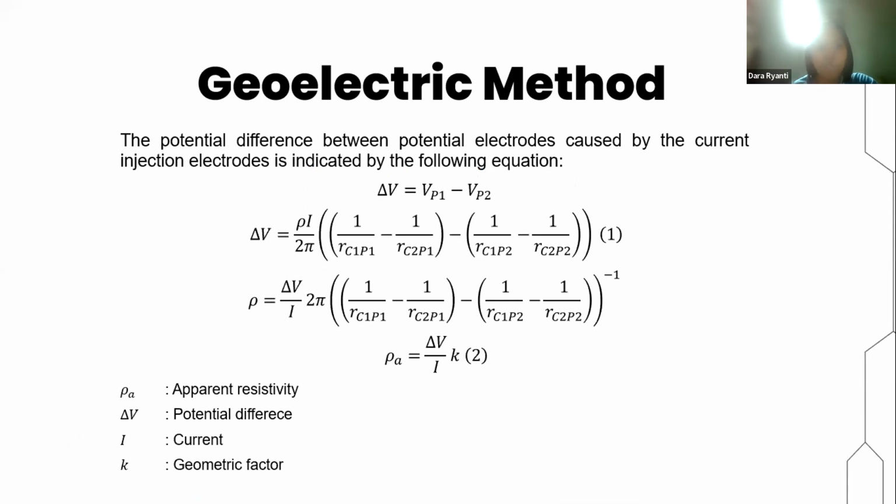Measurements for resistivity surveys are made by sending current into the ground through the current electrodes, and measuring the resulting voltage difference across the potential electrodes. In its most basic form, the resistivity meter has a current source and voltage measurement circuit connected by cable to a minimum of 4 electrodes.